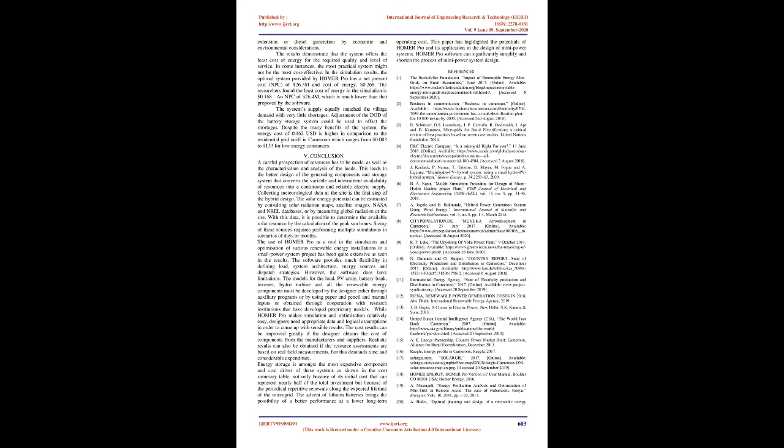The results show that the solar PV rating of 1,800 kilowatts, 16 units of 1 MW batteries, 2 MW hydro generating 1,834 kilowatts peak, and the converter operating at 1,711 kilowatts are the optimal combinations. The dispatch strategy is cycle charging, CC. The net present cost, NPC, is $26.3 million and the initial capital required is $17.4 million.